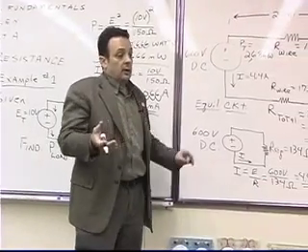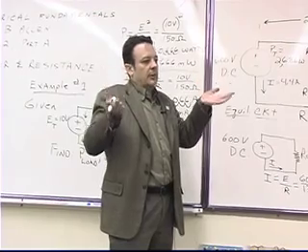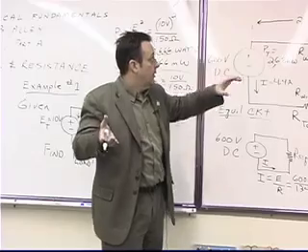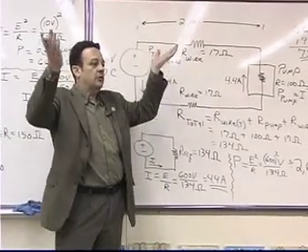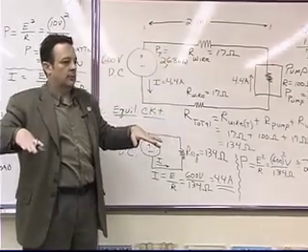One way would be you could buy an inverter, you could step the voltage up, and then by stepping the voltage up, you would reduce the line losses. Because by stepping the voltage up, the current decreases in direct proportion. Right?